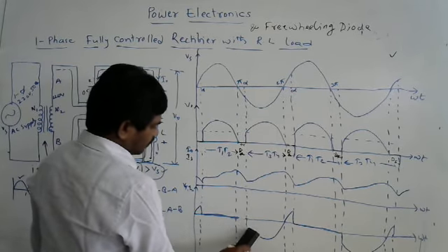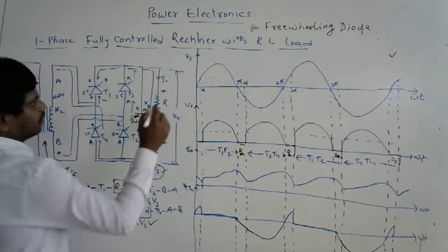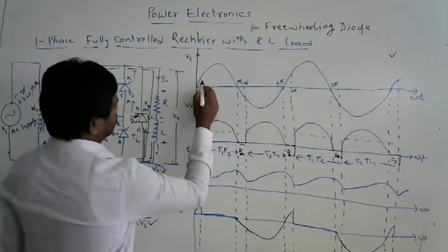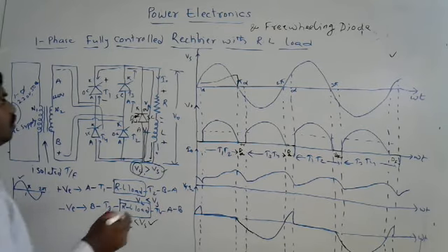And coming to one more. During this period, the input has the same current as the output. Now the input wave is being changed. I am just drawing this input wave like this. Till pi, current is there through the source. After pi, there is no current flowing through the input side, which means the supply current is 0.